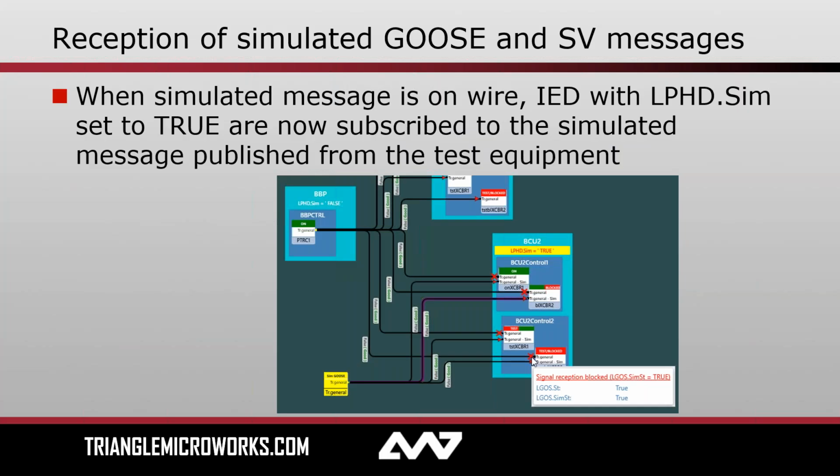You can lift the wire to the trip coil there. You can do the whole test, and the Op OK also has a timestamp, and then you can use it to measure the performance of the trip without the trip really having happened. So that was exactly the purpose why we introduced Op OK. So yes, it goes always through independent of the mode we are in.